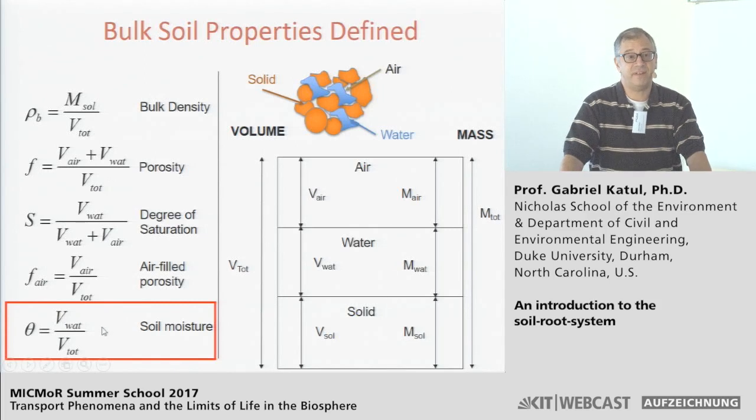By no means is this definition unique. If you look at the engineering literature, especially the pavement design literature, they like to reference everything to the solid volume rather than the total volume. So you might see analogous definitions that are all anchored on the volume of the solid rather than the total volume. Okay.